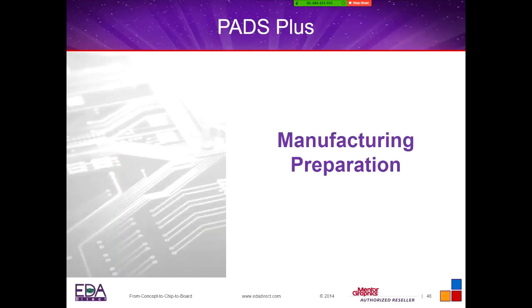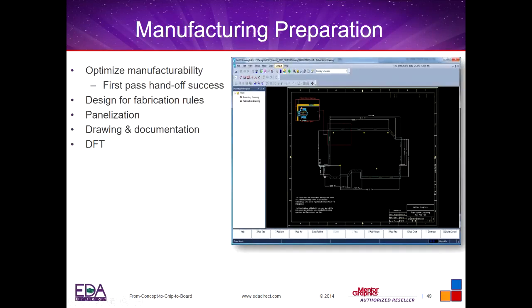You're going to have a manufacturing prep tool. So this does not come with the PADS tools, but this does come with the Pro. So you're going to be able to create your drill drawings in here. You're going to be able to set up everything for your design rules. You're going to be able to panelize if you want to panelize, set up your thieving in here, create all your documentation, as well as being able to do DFT.